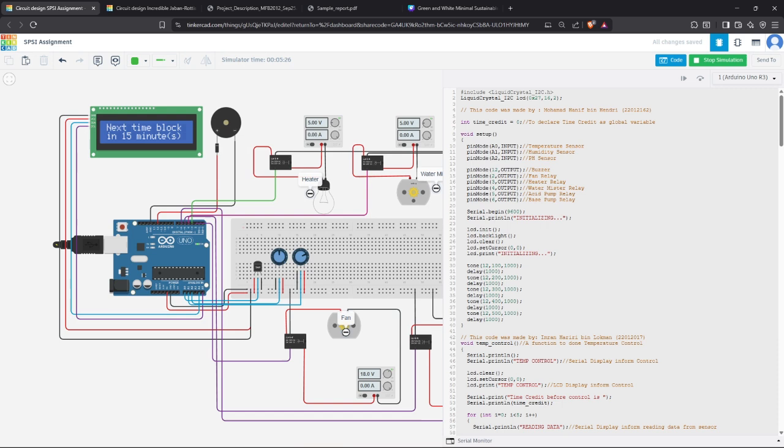First of all, we need to know the library that we include in this project. First of all, we include the LiquidCrystal_I2C.h. We need to include it because we connect the LCD to the Arduino via the I2C with the port SDA and the SCL. Without the I2C, we need to connect many pins from the LCD to the Arduino. Thus, with this library, we could reduce the ports used in the Arduino.